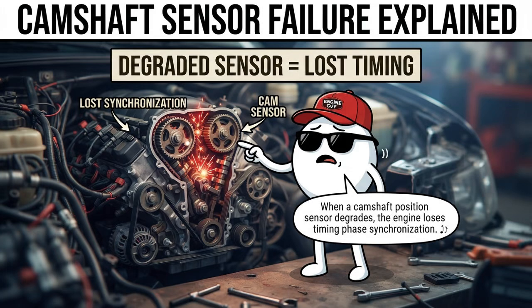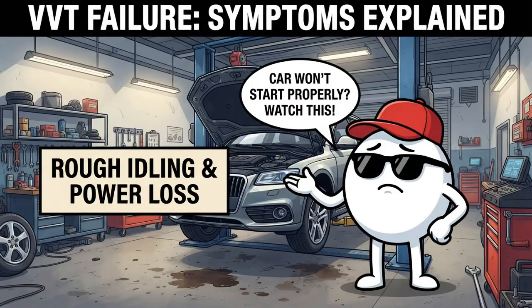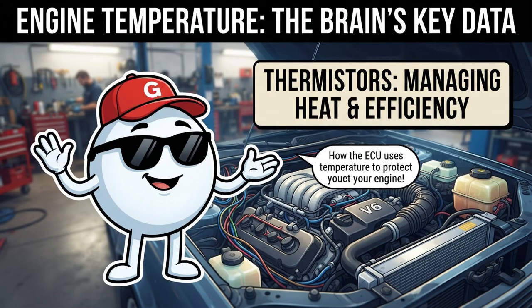When a camshaft position sensor degrades, the engine loses timing phase synchronization. This causes extended starter cranking before the engine catches, rough idling, noisy timing chain operation, and a dramatic loss of top-end power as the VVT system locks out for protection. Liquid and air temperatures dictate basic internal mechanical clearances, oil flow properties, and overall thermodynamic efficiency. To manage cold starts and thermal protection, the computer relies on a dedicated suite of temperature thermistors.